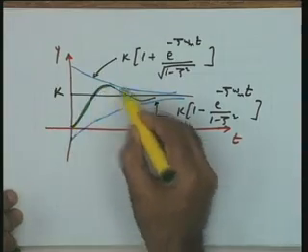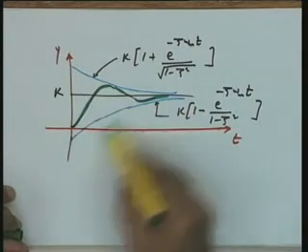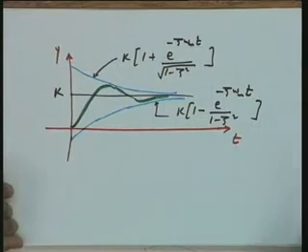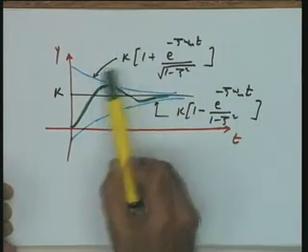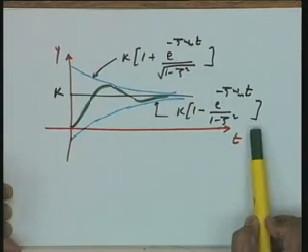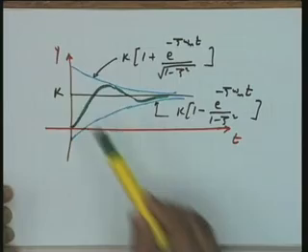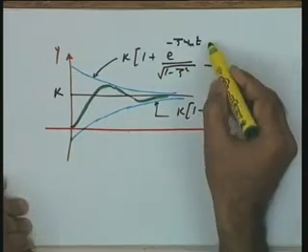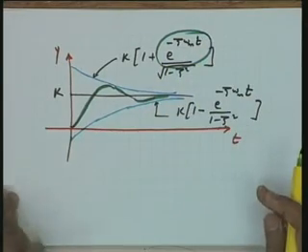Now, look at this place. This is a typical underdamped response I have taken over here, and the blue curve is the envelope of this response. This can easily be examined. These are the two envelope expressions. So, the decay of this response depends upon the decay of the envelope, and this envelope decay is guided by this particular exponential factor.